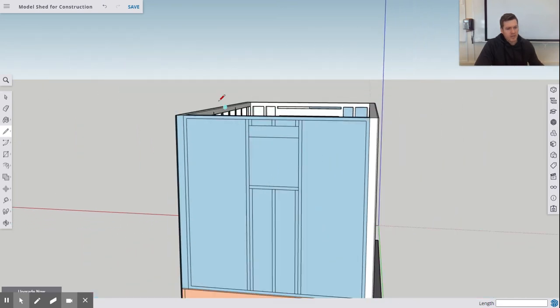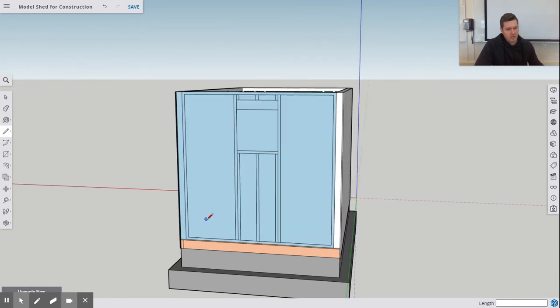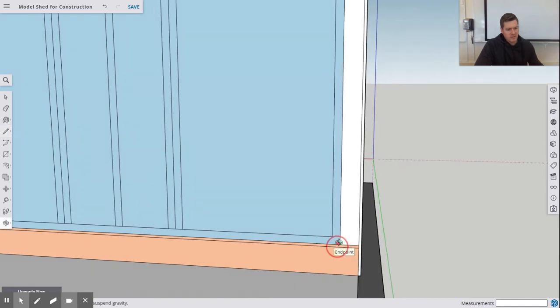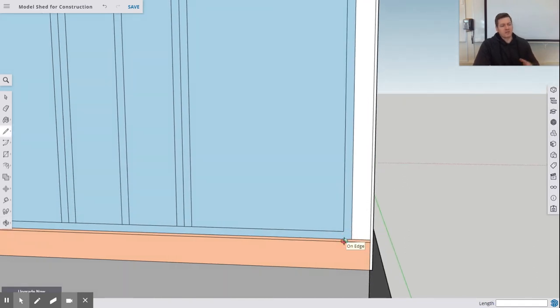Now that we have our frame drawn in, we can actually start drawing in the rest of our studs. So we want to come 16 inch on center from the edge. So once again, if we're doing 16 inch on center from the edge, that means we've got to take off, let's see, 16 inches on center. We want to go 16 from edge, so we're going to come back 3/4 of an inch, and actually 1.5 inches. So I'm going to measure this thing again.